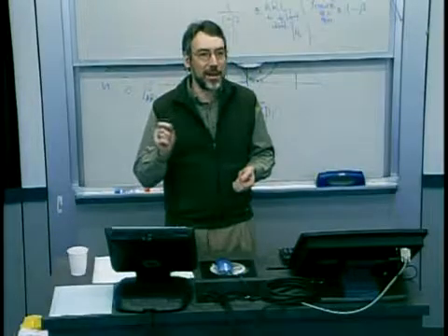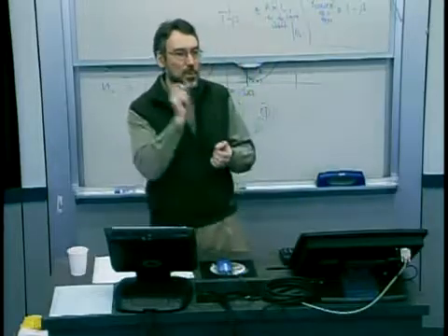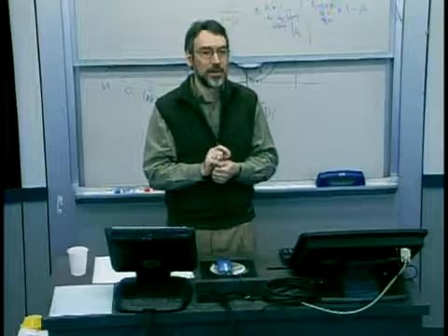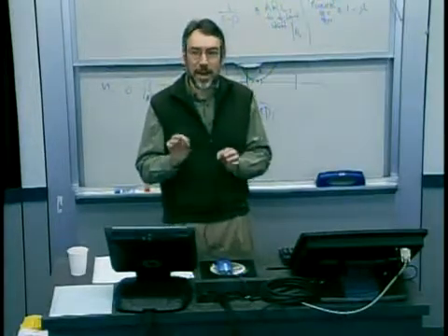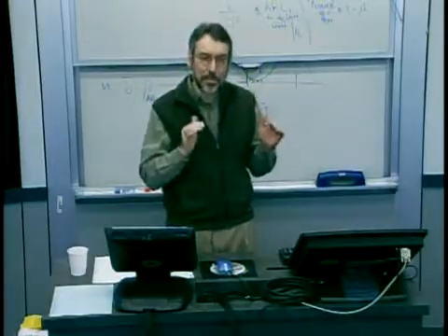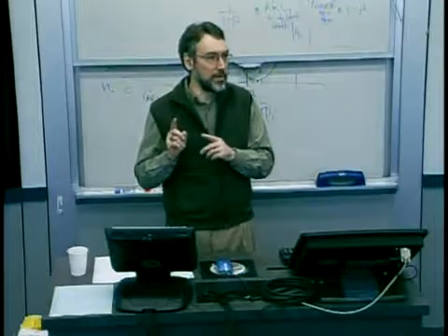You are exactly right. So, in SPC methodology, what you are supposed to do anytime you see an alarm is go and look at the equipment, investigate the problem, and decide, was this a false alarm? In other words, is the process still operating normally, or has something important changed?